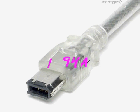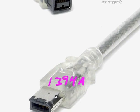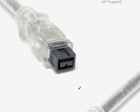And then as far as how the cable looks, this would be a 1394A cable. That gives us kind of this D shape on the end, and there will be 6 contacts in there. This is for the original standard 1394A, and it gives you up to 400 megabits per second. But in this particular photograph, I've actually also got another end of the same cable. The other end of this cable is this. Okay, that looks quite a lot different, doesn't it?